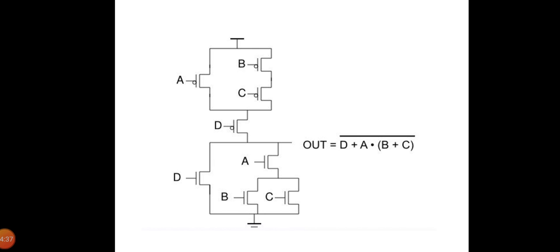Similarly, two alternative approaches to charging up a capacitor are shown, with the output initially at ground. A PMOS switch succeeds in charging the output all the way to VDD, while the NMOS device fails to raise the output above VDD minus VTN. This explains why PMOS transistors are preferentially used in the pull-up network.